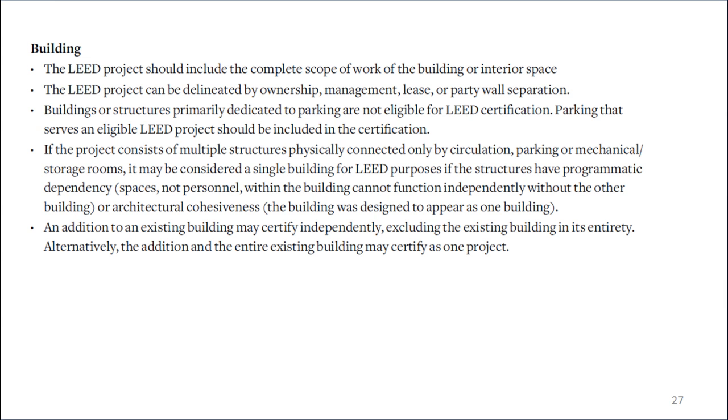Further additional guidance. Building. The LEED project should include the complete scope of work of the building or interior space. The LEED project can be delineated by ownership, management, lease or party wall separation. Buildings or structures primarily dedicated to parking are not eligible for LEED certification. Parking that serves an eligible LEED project should be included in the certification.